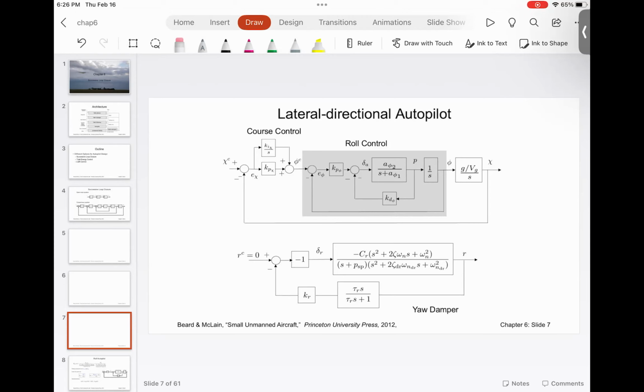I'm going to reduce. Once you reduce, and we did this block diagram reduction in robotics 1, wherein we combine these blocks, and after combining these blocks, we got this big transfer function. And remember, we linearize, which means whatever we are going to get is all linear. And whenever you have a linear system, the beauty is at the end, it will be in the form of a spring mass damper system. So now I want you to observe this.